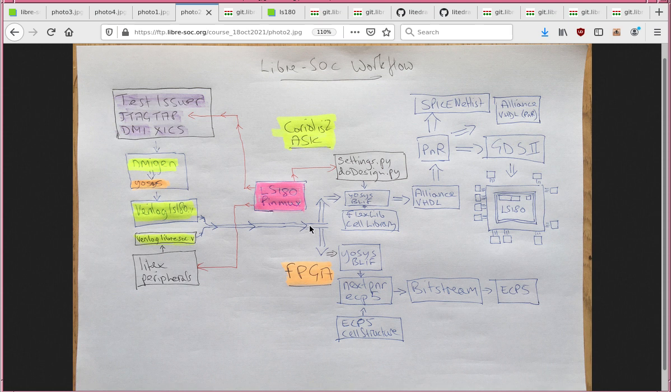Taking the same route, going back to the ASIC, again, interestingly, it uses YOSYS, and this time it compiles to BLIF. And at this point, remember that YOSYS doesn't necessarily know about the geometry and the cell library, what the cells actually have. So you have to tell it.